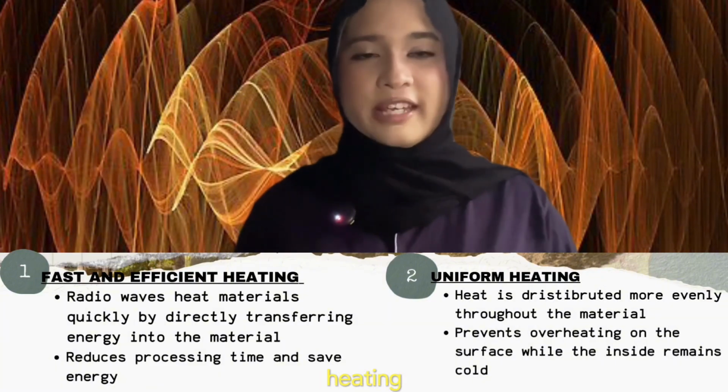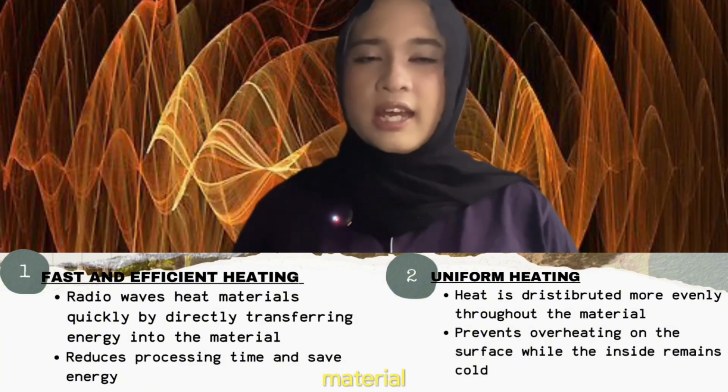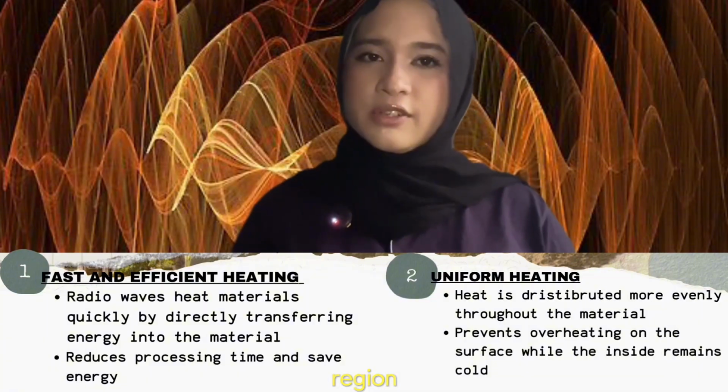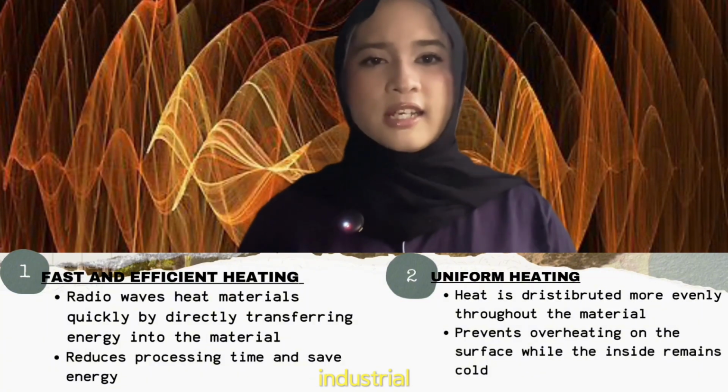Secondly, radio wave heating provides more uniform heating. Because the energy can penetrate into the material, heat is distributed more evenly throughout the object. This reduces the chances of overheating the outer surface while the inner region remains cool. The characteristic is especially useful in food processing and industrial manufacturing.